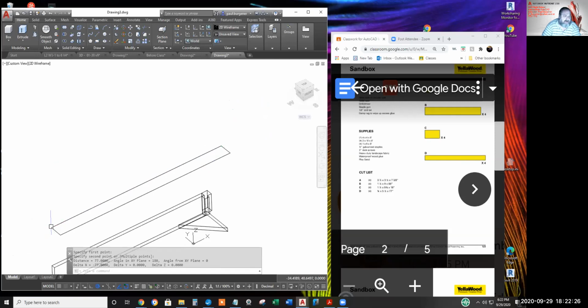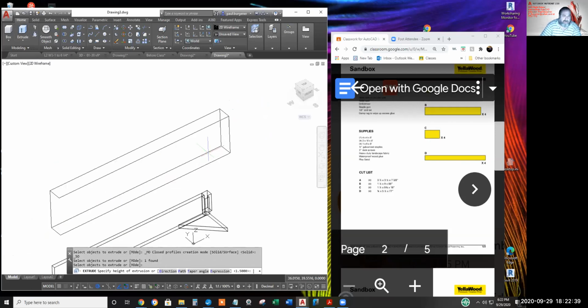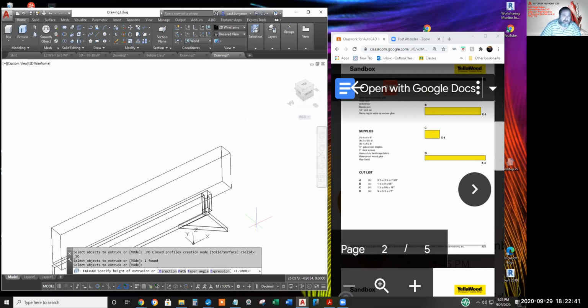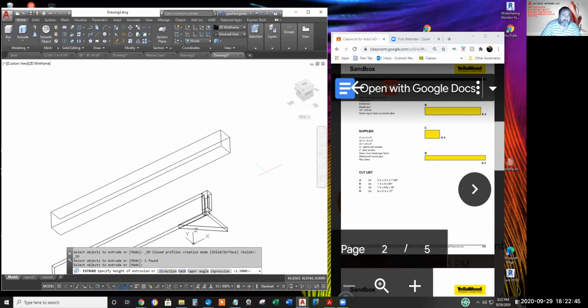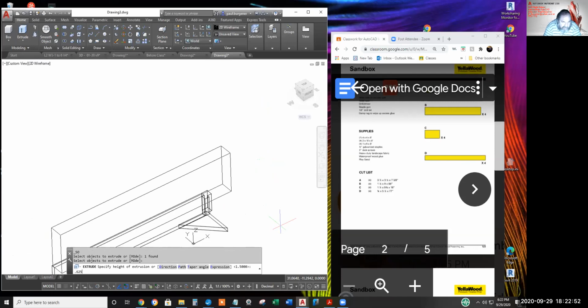From there to there is 77. You can extrude this 5/8, nope, 3/4. Again, the extrude command does not recognize where your cursor is, so I can be down here and type 0.625, enter, and it'll go upward.